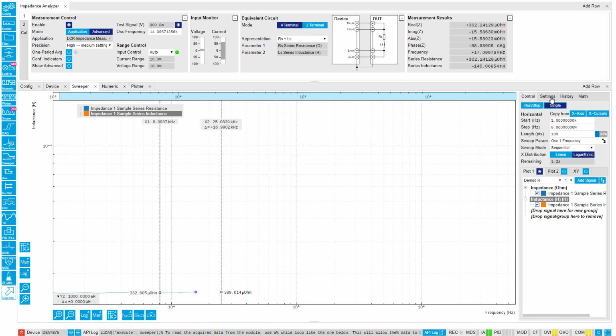For the DC-link capacitor, the ESR measurement is mostly relevant in the lower kilohertz range that we can see here for the ESR values, and starting from the resonance frequency of the capacitor, also the inductive contributions start to play a role here. It is clearly visible that the ESR firstly is at a constant level. We can also do some specific measurements at a fixed frequency here, for example at 8 kHz and 25 kHz, and we can obtain some inductive peaks here in the higher kilohertz range.